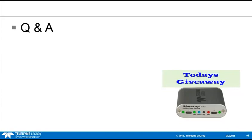But you can obviously tell by physically comparing them, at least the ones we've seen. Now, with an analyzer, it's also possible to see cable messages. If there are no cable messages, that could indicate that you're talking to a cable that doesn't support E-markers.